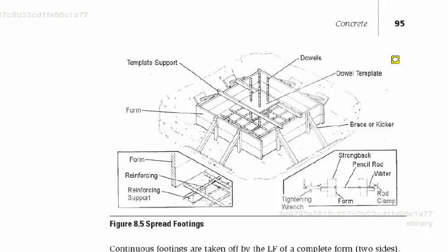when you're building that footing, there's excavation. Obviously, there's forms, there's support materials, lumber. You have the rebar that has to be inserted, then the concrete. So there's a lot of different pieces, and that's what you need to do, and make sure that you've included it at least somewhere on your estimate. We don't want you to double count anything, but make sure that you have everything that you need when you're building a piece of work.